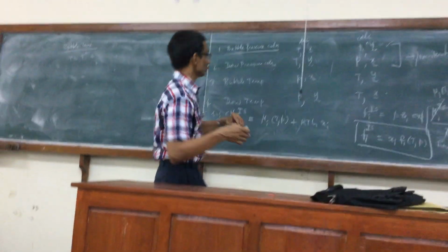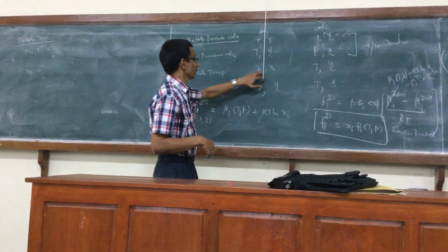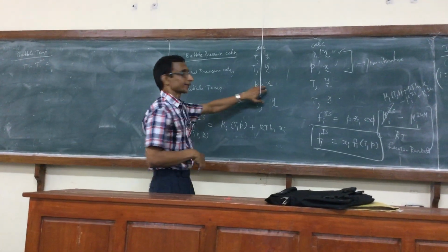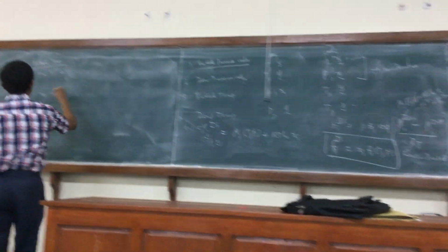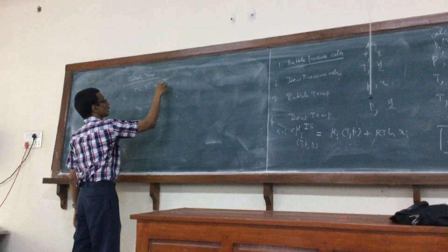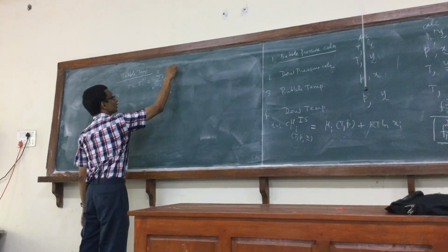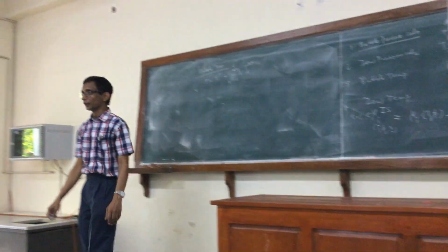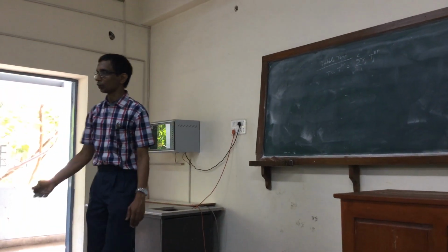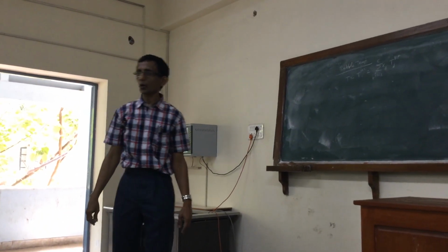So we can use the same idea. So the bubble temperature here, x is given. So a good initial guess would be the sum over j equal to 1 to C of xj Tj, the pure component boiling point of j. That might be a good, it might be a linear combination.